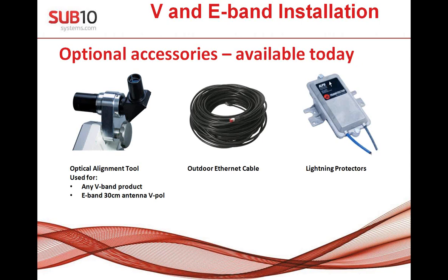It's our high recommendation to protect the system with an LPU kit, but it's your decision. It's not necessary for technical functionality, but it provides higher protection. Later on there will be a picture or scheme regarding recommended protection on the link. If you would like maximum protection, you have to use 2 LPU units on each side, because one is located close to the terminal, and the second is located where the cable goes into the building.